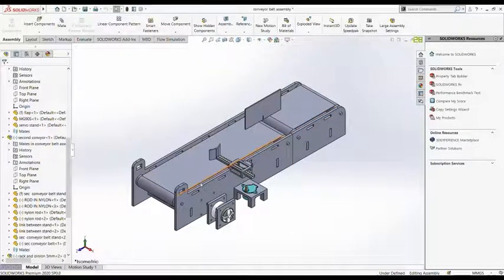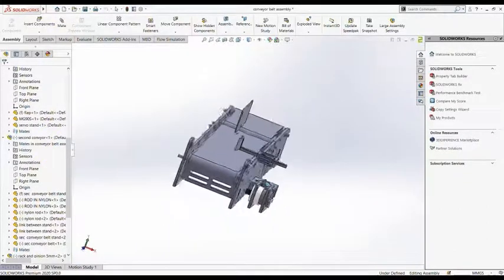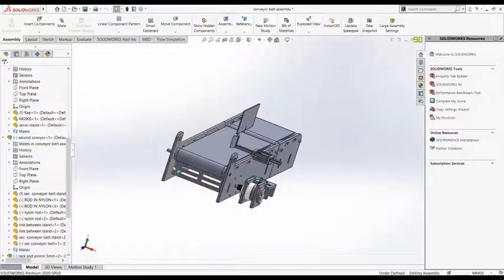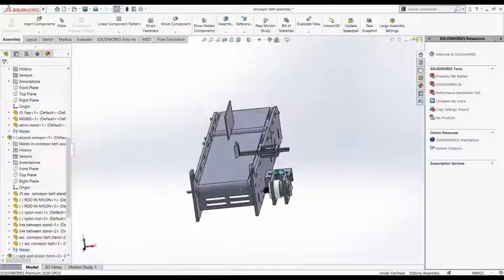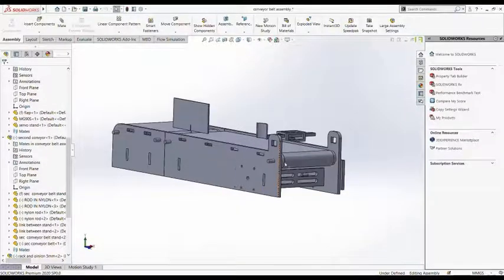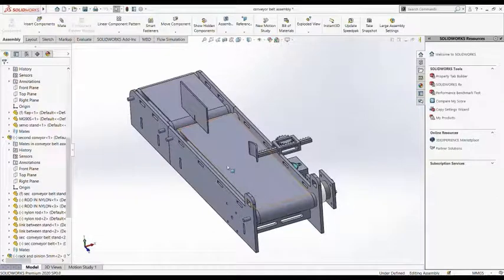The larger one helps in the movement of the bottle through its measuring phase until the separating phase, after which the movement is taken control by the smaller belt. How is it made? The conveyor belt has two parallel sidewalls which are supported and held by a pair of eye structures. The sidewalls are made of fine acrylic sheet, and each conveyor belt holds two nylon rods of 24 mm diameter, all lathed to specific dimensions.